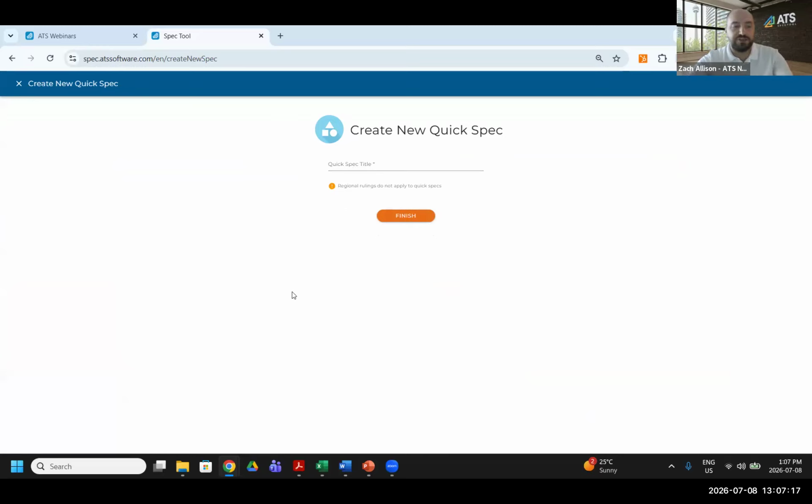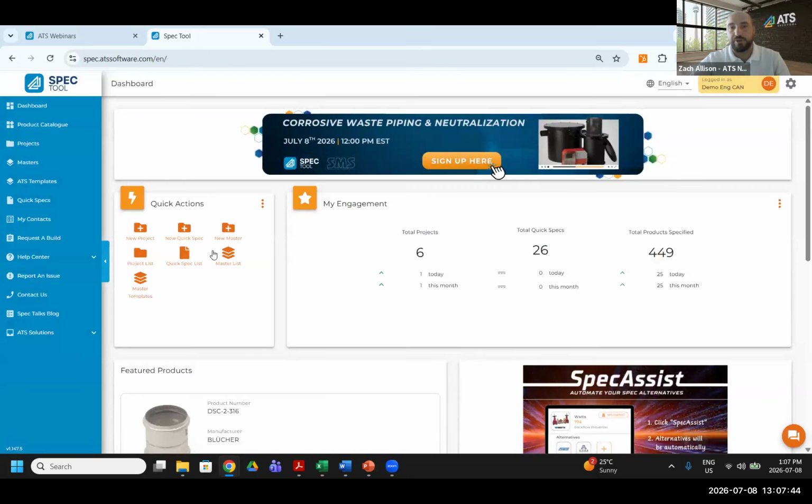This does come into play across Canada now, especially as we have our new NRCan updates. If you have not updated your masters, there's some different applications. Healthcare has different flow rate allowances than office buildings or general public applications now, which has a different flow rate than your residential application. So your shower for your residence is going to have to be different than the shower for your office, and that's important to keep up to date. That's what our masters and projects are for. If you are just creating a quick spec, you are not getting that protection.